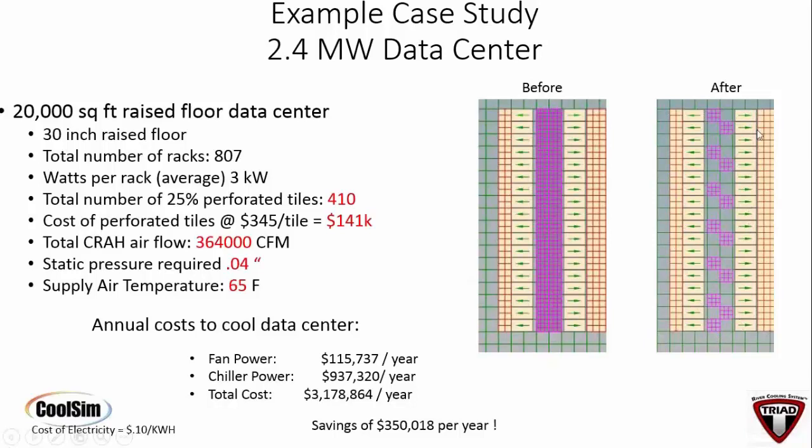The answer is that we did an analysis assuming the air was coming from a single direction. In fact, air under a floor comes from every direction because there's a lot of turbulence under that floor. So the effect we're showing you on one cabinet is actually spreading out onto the others as well. Is that what you've seen in practice?